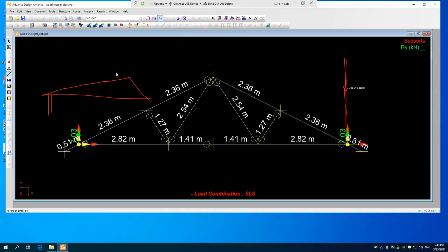Now, if it happens to go over, that's why I want you to appreciate one thing. Why do we double the plates on a bearing wall? Because sometimes the member doesn't fall exactly over the stud below it, and this acts like a little built-up beam to help transfer the load to each member. You understand?